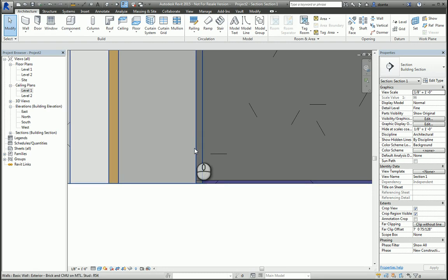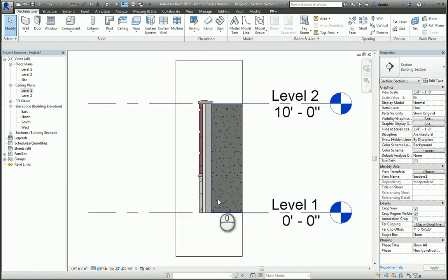If you don't have a base, and you just want that chipboard to be constructed all the way down to the floor, and have the tile go and meet up against it and basically hide that really bad edge of that cut of the chipboard, then you would want the edge of the floor to be at this line, not this line. So just little things like that to think about when you're putting in a floor. And so that is your command for